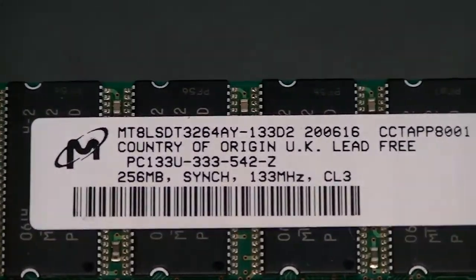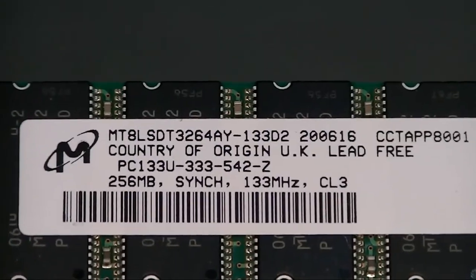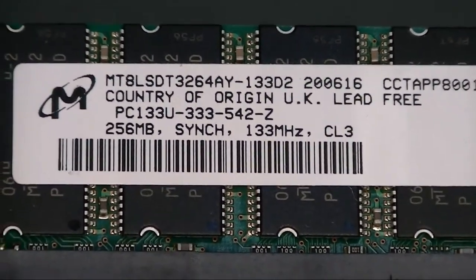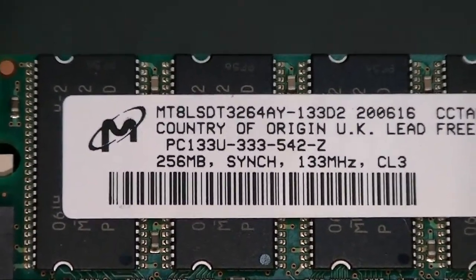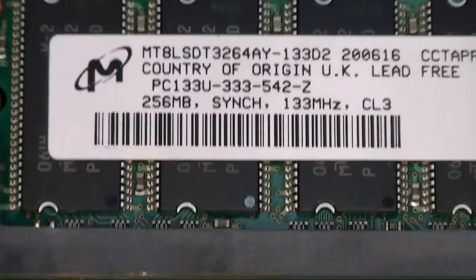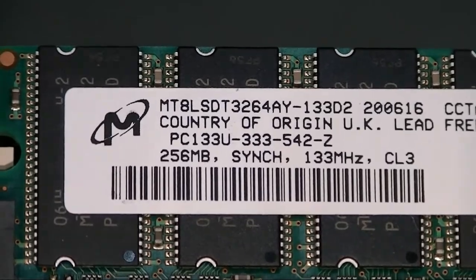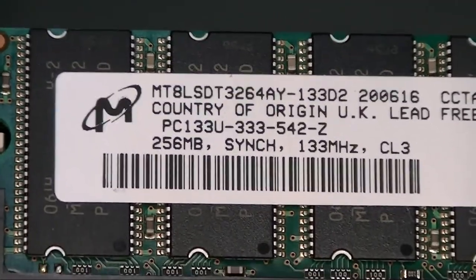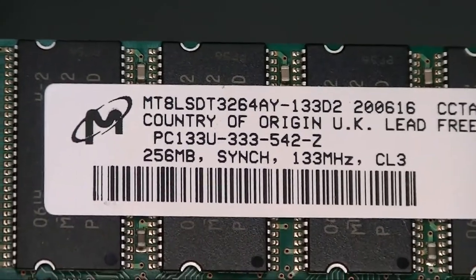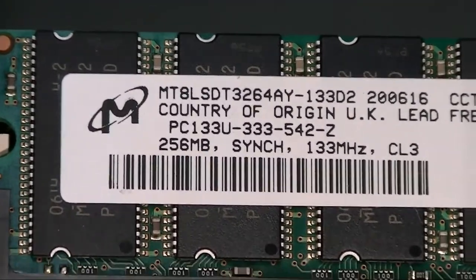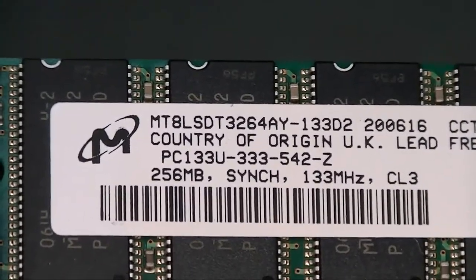We determined, like I said, probably an 866 megahertz Pentium III, and this is PC133 RAM, and so effectively this means the CPU on this single board computer has a front side bus of 133 megahertz. So the clock multiplying to the CPU would normally be a multiple of that 133, and so it makes sense for that 866 megahertz CPU if that's the case.